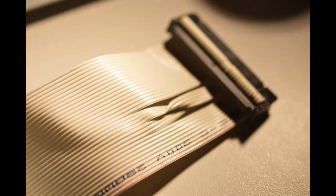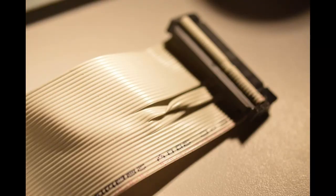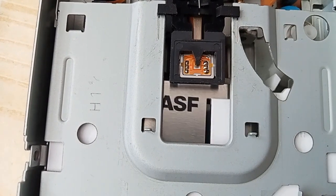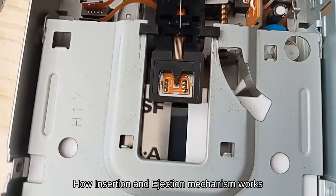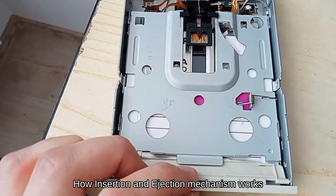The floppy drive flex cable has a twist, which redirects pin 16 to pin 10 and pin 14 to pin 12. This makes it possible for the disk controller to control 2 drives on a single cable without any kind of jumpers. Lastly, the floppy disk drive does not perform any logic or decoding on read or written data. It is a simple analog device.